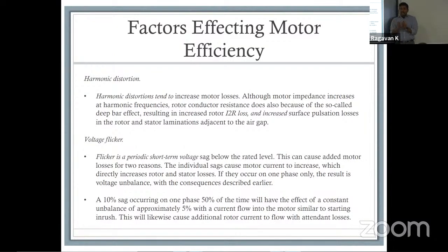If you're putting it inside, that has always been the constraint. There's a couple of things. First, you had to figure out how big your circuit can be. Because if you're talking about SMDs, great, but you still have to go smaller than that, right? You have to change the packaging so that you can have more components. Then you had to look at how much noise you're going to radiate and how susceptible to EMI that converter is. Remember, electromagnetic fields are susceptible to distance. If you keep it very close, all the noise in one system crosses over to the other system, which means now you have solved one problem, but you have to answer another. I'm not saying you have created another one, but you've definitely gotten a lot closer to another one.